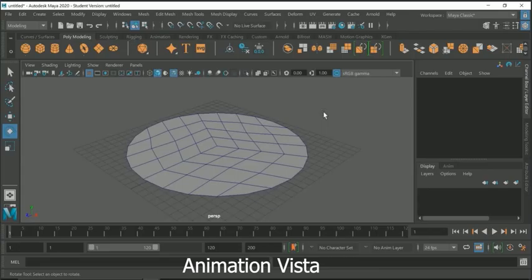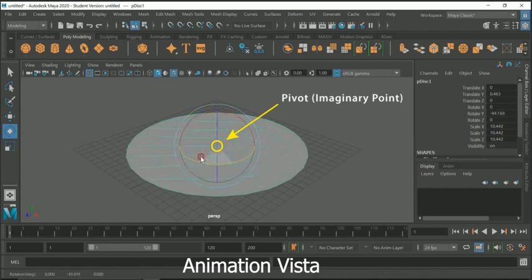In this video, I am going to show you how to manipulate the pivot of an object in Maya. Alright? The pivot of any object usually lies within its geometric center. It forms the point around which an object rotates. Now, in Maya, the pivot of an object can be manipulated by activating the pivot editing mode. While the pivot editing mode can be activated in many ways.